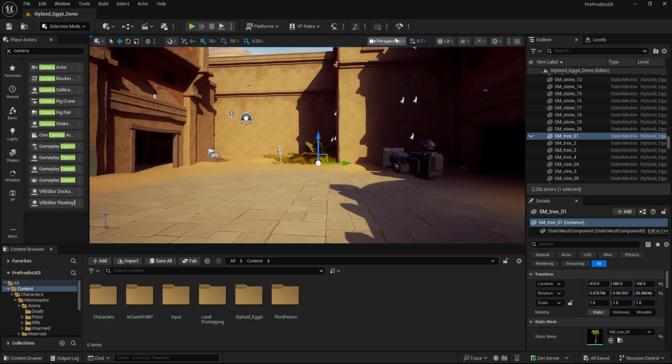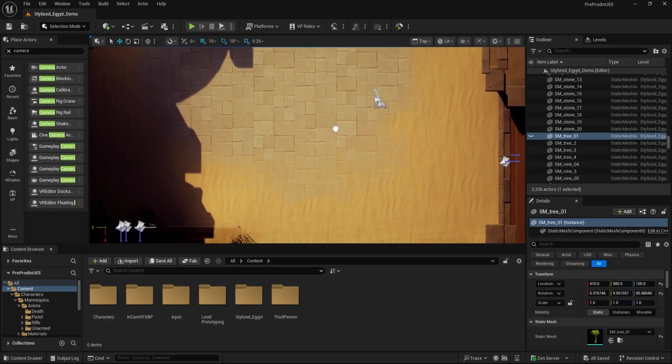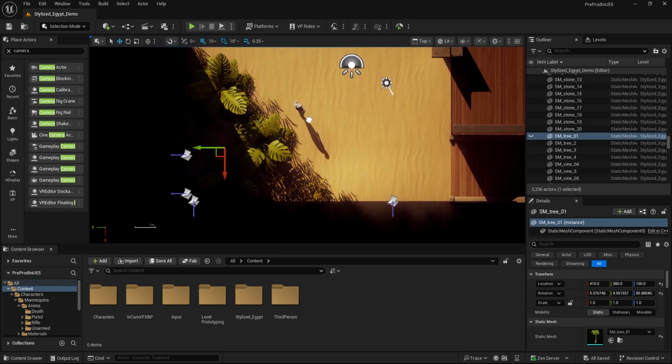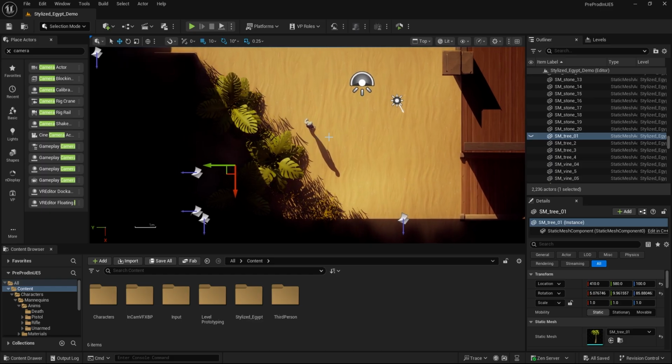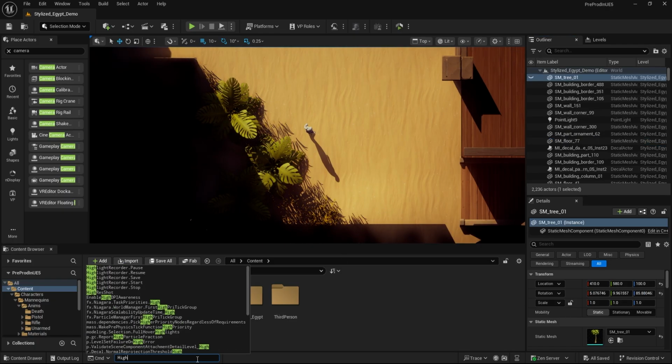Within this top view, we can move around by holding the right mouse button and moving around the space. We can also zoom in and out through the scroll wheel. An important note is that, unlike the viewport camera, this is a true orthographic view and as such can be relied upon for accurate measurements. If you need to move or hide objects within the viewport, you can do this the same way as you would with the first method, but as you may have noticed, the top orthographic view will cut away from objects that are in the way, although the settings of this can't be configured and it may end up cutting away things you may not wish for it to do so. As expected, we'll use the high-res shot command to output our image.